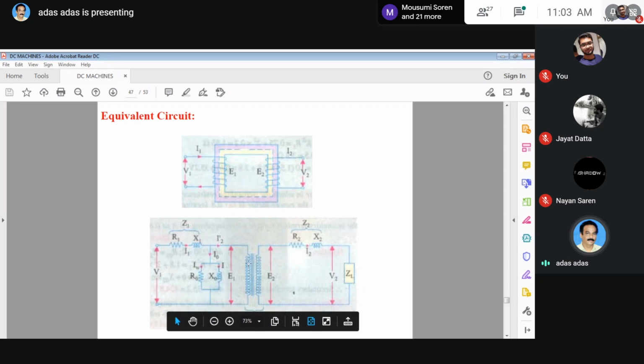Once again, there are two coils which is for the ideal transformer. If you connect the lumped parameters R2, X2 and R1, X1, it will give you the practical transformer. Now, apply voltage V1, current I1 flows. I1 has two components, I0 and I2 dash. I2 dash comes due to the reflection of I2, and it supplies the load current, and this is the magnetizing current. It has two components, one is I mu, another is I omega. And two parameters are there, X0 and R0.